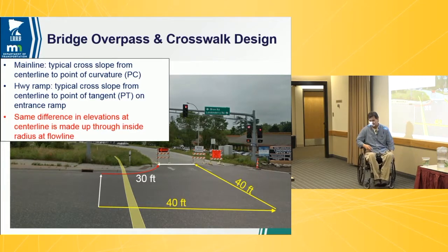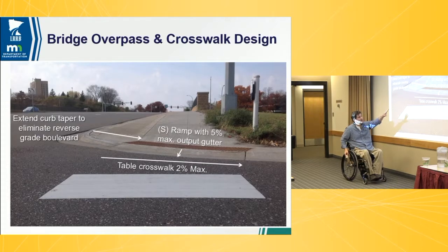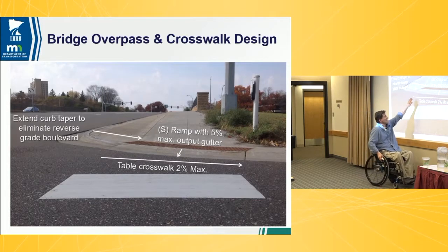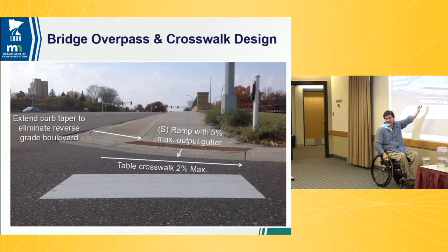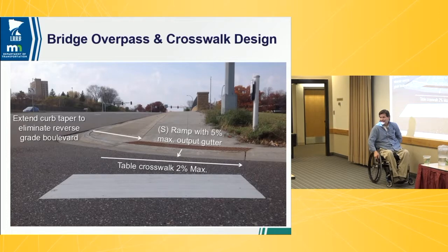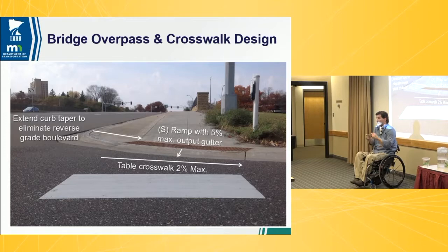And ultimately, I'll show you the third in a sec. But this is what it looks like. You definitely want to hold this at the same slope as your mainline profile. Again, when this starts diving down, this curb ramp starts off much lower, so you're even below gutter grade over here. And then you've got to fight up this hill. Actually, you're not only fighting up the hill that we put ourselves in, but you also have to make up that curb height of 6 or 8 inches. So that's the third factor that's working against me.